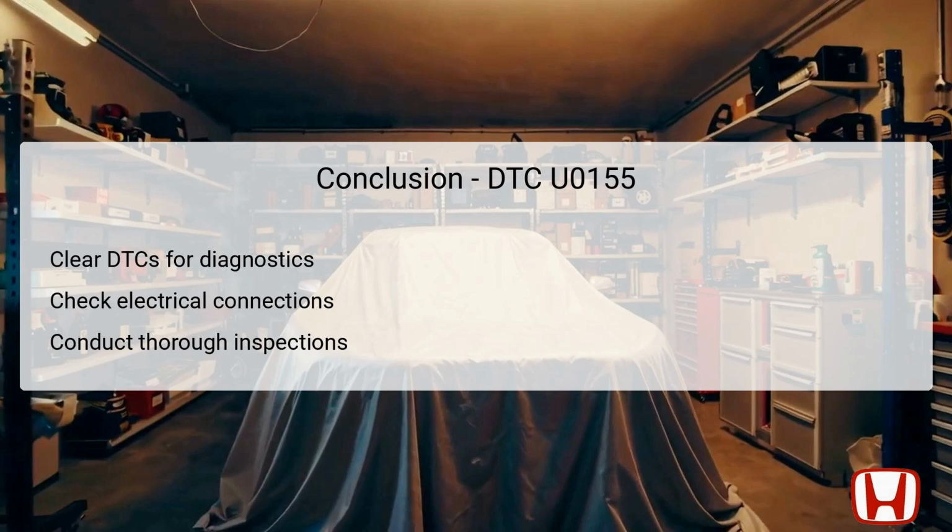In conclusion, addressing the U0155 DTC in the 2008 to 2012 Honda Accord requires a systematic approach to diagnosis and repair. The essence of troubleshooting begins with clearing DTCs using the HDS and determining if the fault is intermittent or persistent.